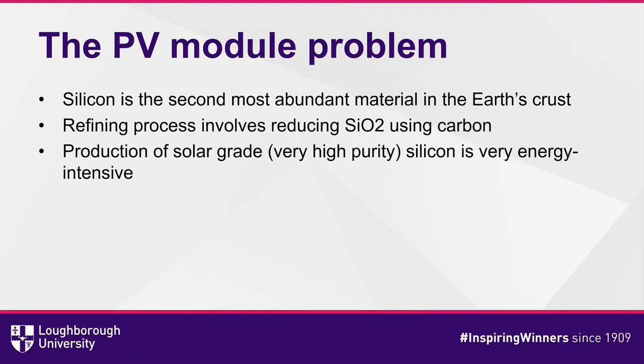They all tend to work with a particular material called silane, which is a very unpleasant material, and I think it's toxic and explosive. Either way, it's quite a nasty material to work with, and it involves very high temperatures and quite significant energy input as well. So it's really not a good process. It's the most effective way that we have at the moment for the refining of silicon, but it's really not a good process to have to use.